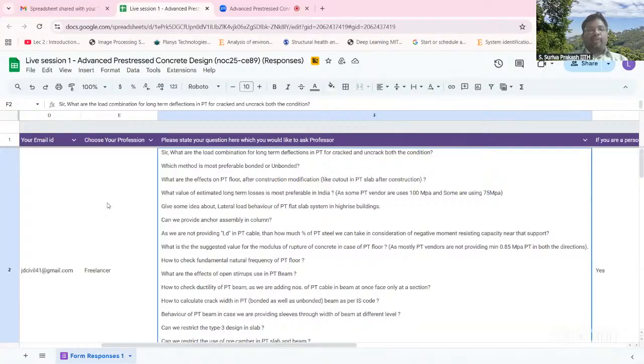Though their primary role is to transfer only the gravity load, not the lateral load, they should also have a minimum level of drift capacity, or I should say lateral displacement capacity, before they collapse, because the lateral load system takes care of the wind and earthquake load.